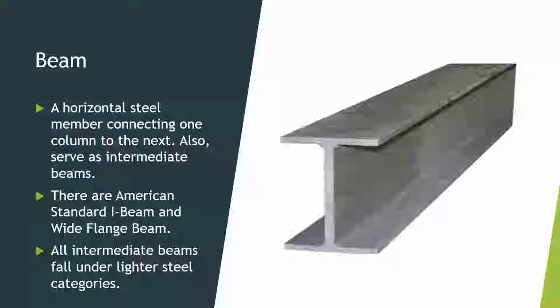So let's look at that 12-inch first. That 12-inch is not exactly 12 inches. It's a nominal number given to that designation. So that 12 could actually mean 12.19 inches. It's always off just a little bit. The 85 that you have written down in front of you is 85 pounds per foot. So for every foot of that beam, it's going to weigh 85 pounds. The WF is wide flange, which we just discussed, one of the different designations you can see on a print.